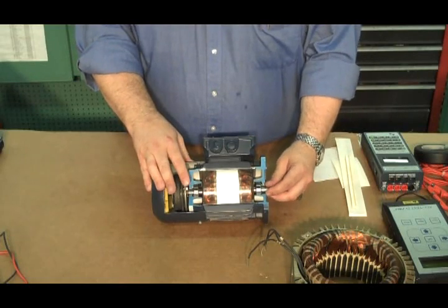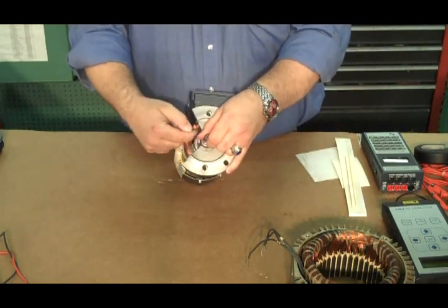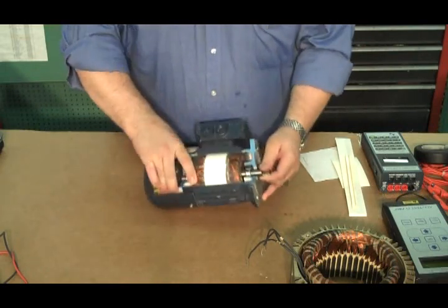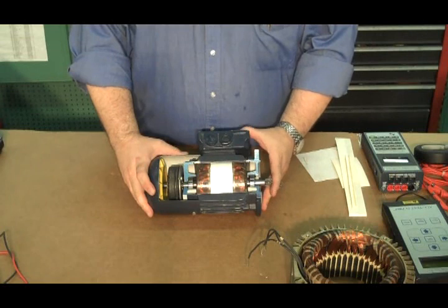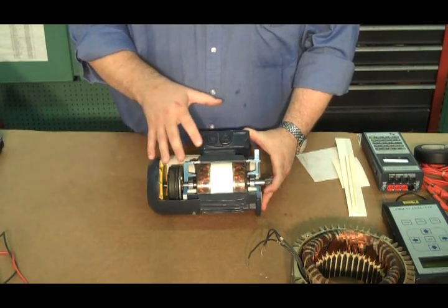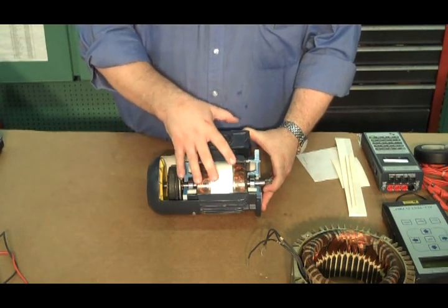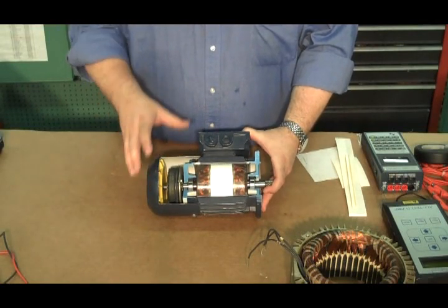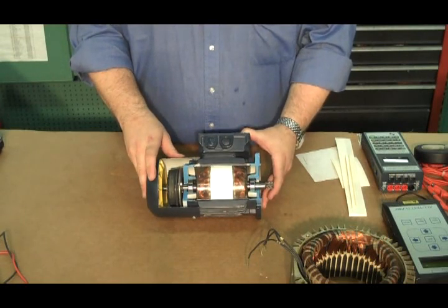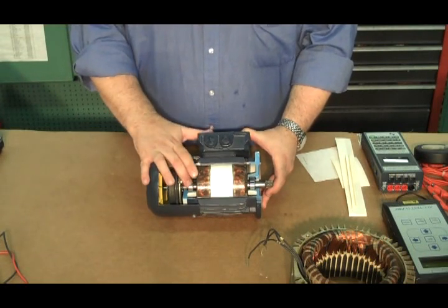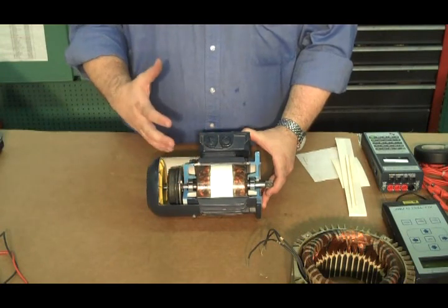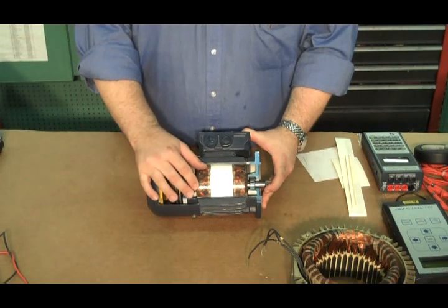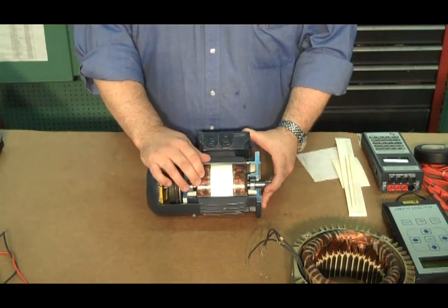And we want this rotor to be within this motor as concentric as possible, so there's an even air gap all the way around. An electric motor is a very precise piece of equipment, and the idea is that as long as everything is concentric and even and smooth, it'll operate just fine. Now, the key components that usually fail in electric machines will be the bearings, primarily, and in much larger machines you might see the rotor bars fail. But what we're going to concentrate on is the insulation system, the windings.